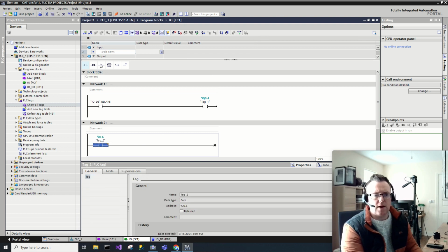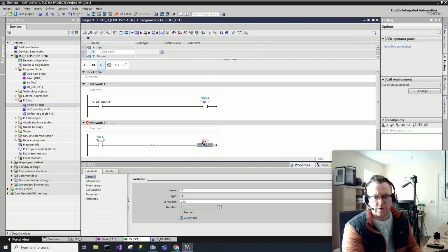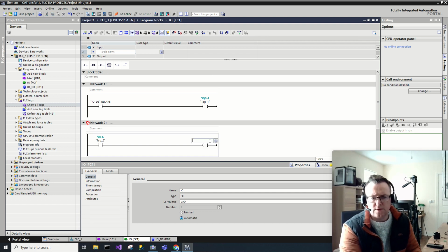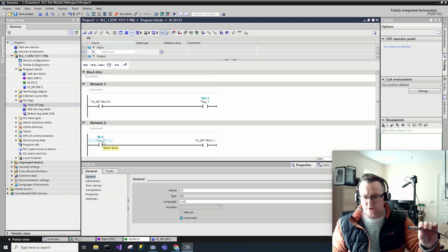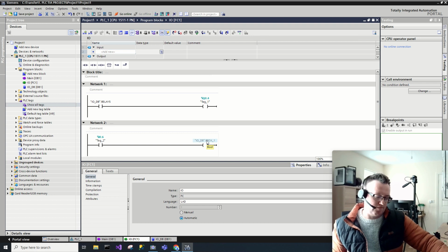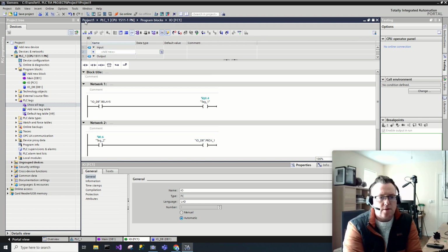So there we'll have it there, and then I'm going to create an output, and the output is going to be our software variable. So if I go in here, and we'll go into IODB, and then we'll go into prox1. So that's basically it. So every time that this proximity sensor goes high, prox1 is going to go high also in our program. Okay, so what I'll do here is go up and save the project.